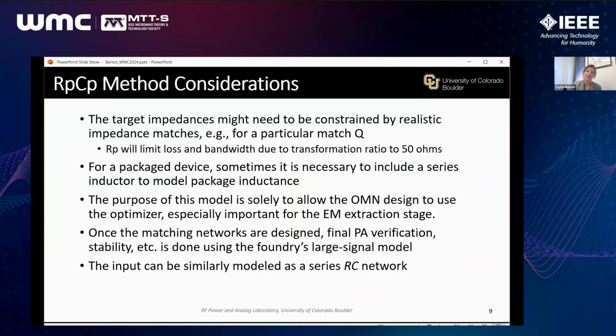So these are some comments on this technique. It works. This is a technique that we find works very well with MMIC design. It does not work so well with hybrid design because it does, of course, not capture any of the package parasitics. But if we are able to work at effectively the actual drain of the device or very close to it, then you can use this as a starting point for understanding the behavior of your particular model.